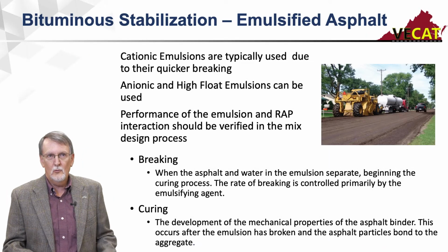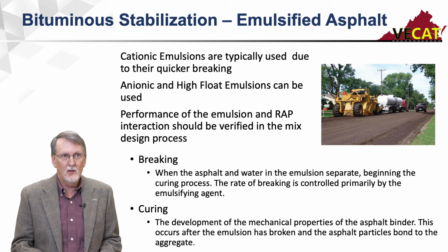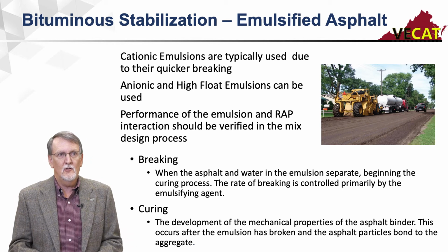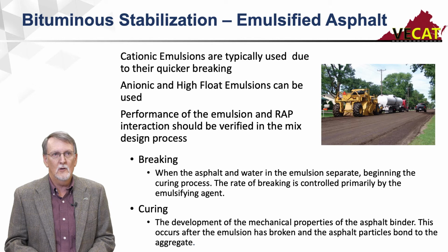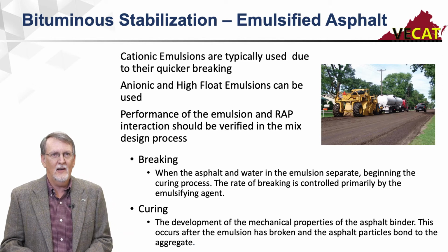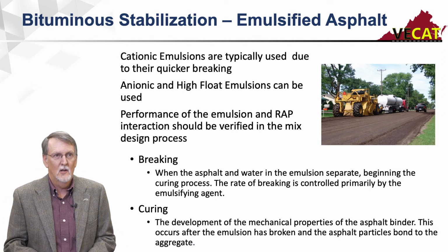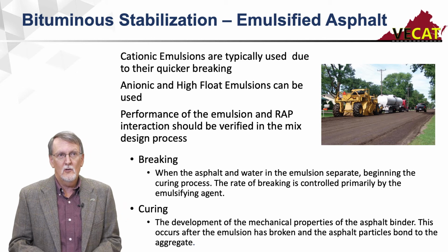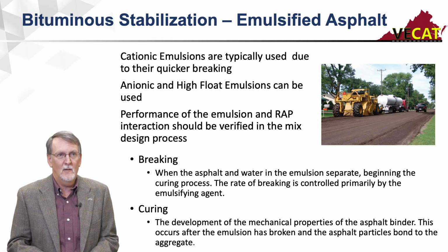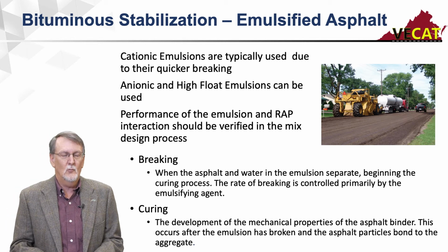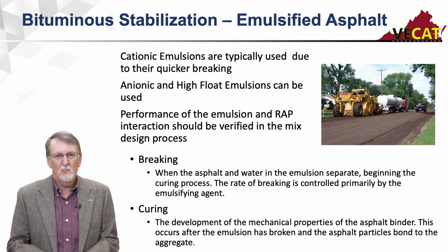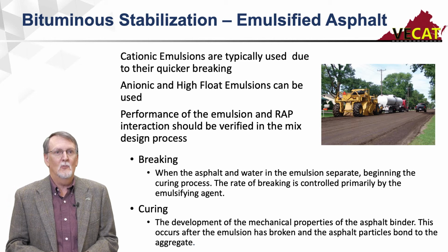As far as what we use, emulsified asphalts, cationic emulsions are what's typically used because they break a little quicker, although we have used anionic and high flow emulsions in the past. One of the things you do need to do is you need to perform a mix design. You need to do that on cementitious as well. With mechanical and pulverization, there's no mix designs. We only run a proctor.